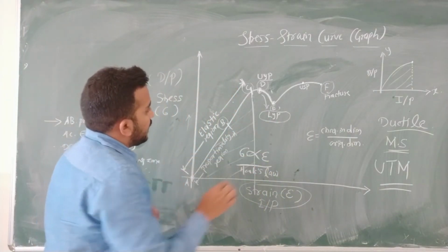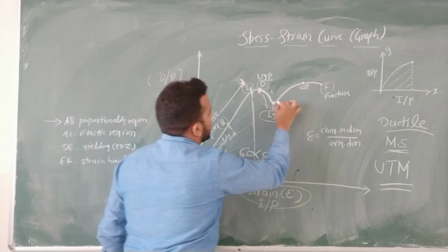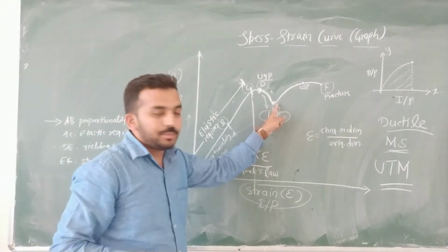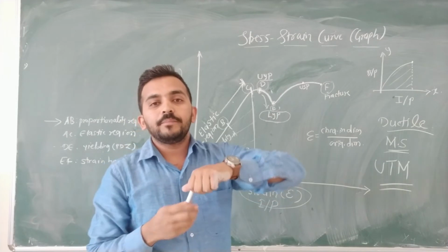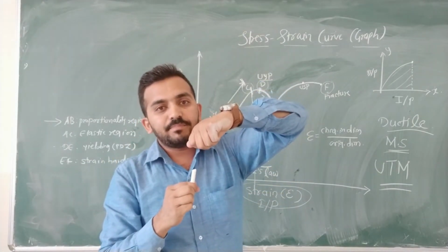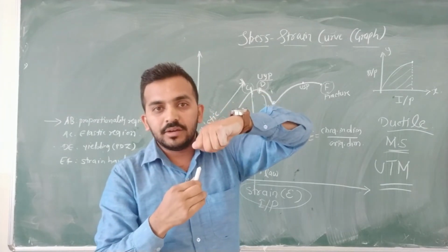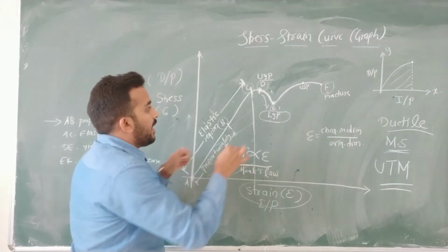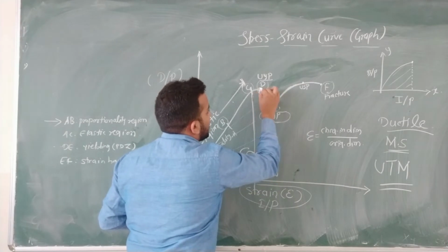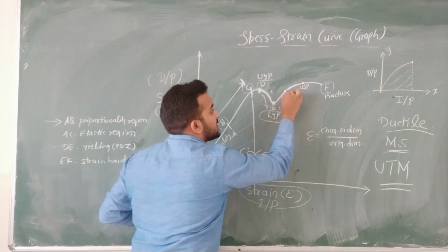Okay. Now we see that the curve again starts increasing upward. Why has this happened? The first plastic deformation is completed now. Let us suppose this is a rod. It is stretched, for instance, plastically. For another set of plastic deformation, the fibers will reorient and they again resist, therefore stress increases. Here the stress decreases, then again they start resisting another change, and the stress is increasing.